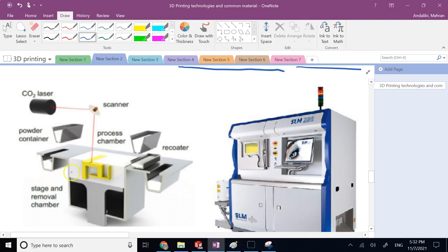And then the powder is going to cover one layer on the print bed. There is basically an arm that grabs enough of that powder and then brings it onto the print bed. And then here you have a CO2 laser, and again you have these galvanometers that will shine the laser at the places where you want the powder to be sintered or melted together.